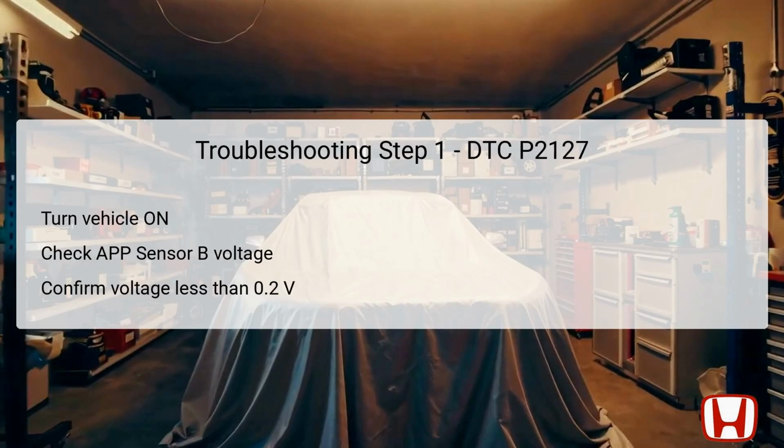If the readings indicate a failure, further investigation into the sensor or its electrical connections will be necessary to locate the root cause of the low voltage output. Documenting the voltage findings is also essential for referencing during follow-up steps.